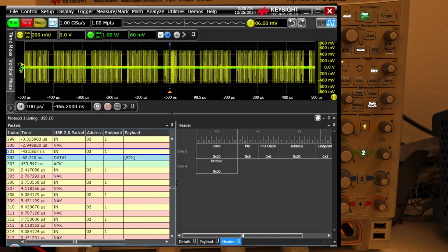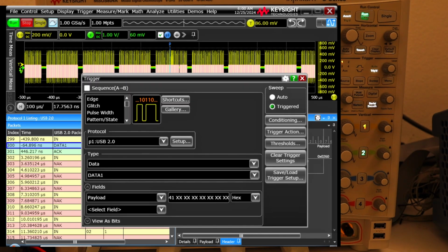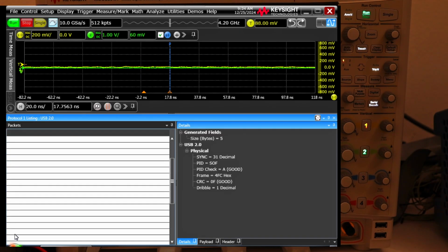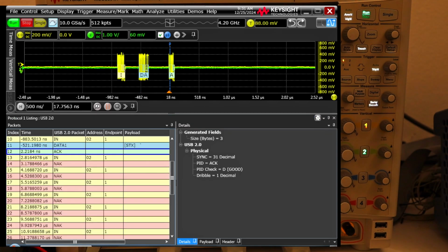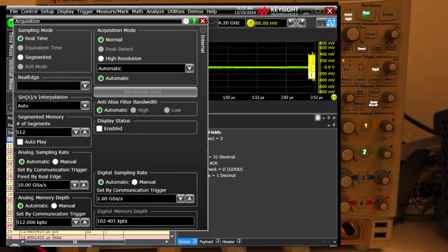I still do not see it. I see the data being transmitted, but I still do not see it being received or transmitted. No trigger at all. I assume that this transmission of data in this FTDI chip is a little bit different than the Texas Instrument chip. That's because the data on the USB bus is going to be transmitted through data packets, and for some reason we cannot trigger on these data packets. So now we are capturing on data. Now we will stop it.